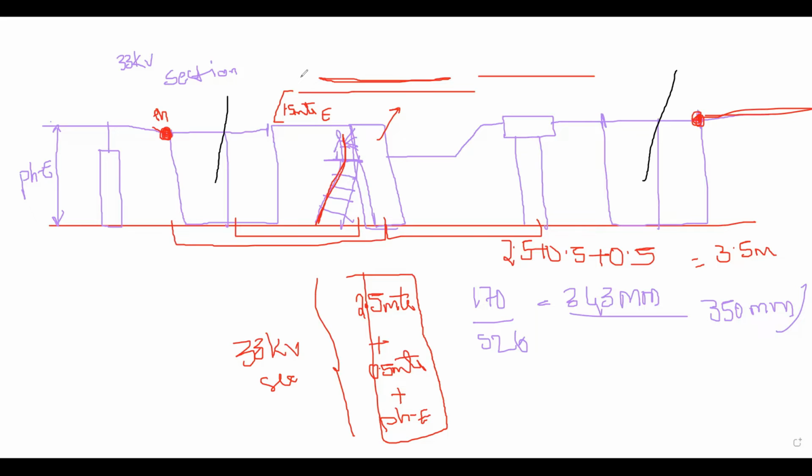These are the main questions they will ask, and you will make an impression at that time when you answer these, because mostly no one knows why we maintain the sectional clearances and safety clearances. They generally talk about phase to phase and phase to earth. They don't know about the sectional clearances and the ground clearances. It is good if you talk about these also in the interview when they ask questions on the layout. Definitely, you will get a question on the layout when you face an interview for substation designing.